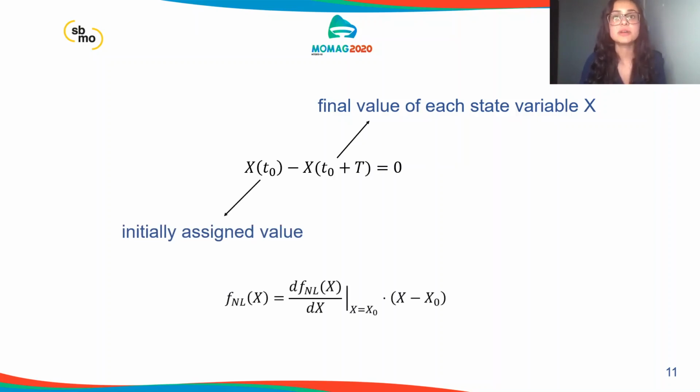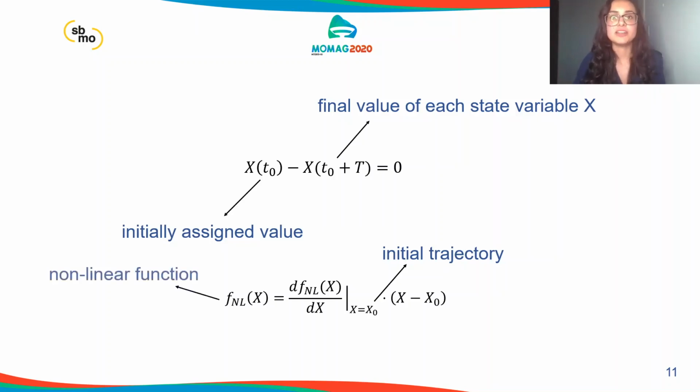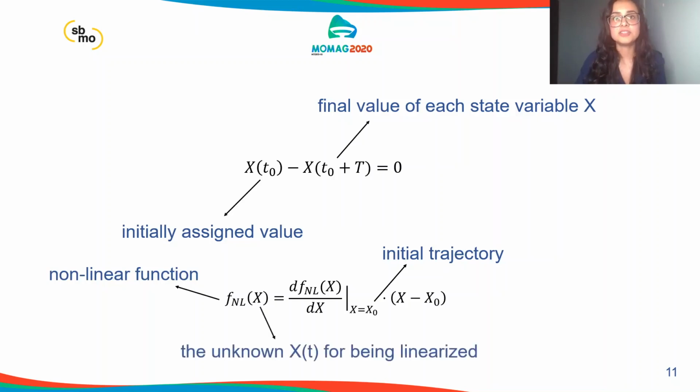The differential equations presented in the circuit mathematical models are discretized and integrated at each time step. In general, differentiation of the element equation in relation to an initial trajectory is necessary for linearizing it. For example, the linearization of an unknown is shown here, in which x0 is the initial trajectory, and f is the nonlinear function of the unknown x being linearized.